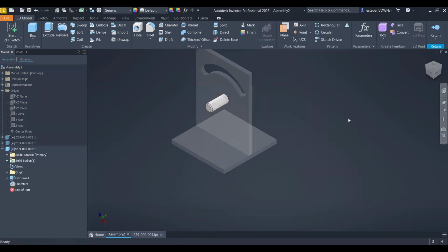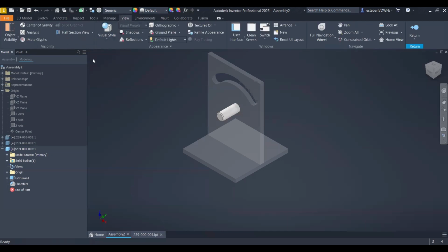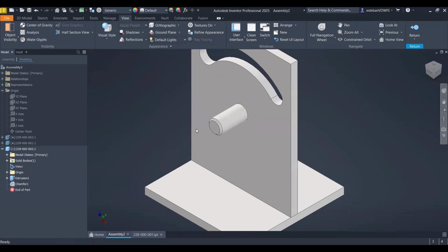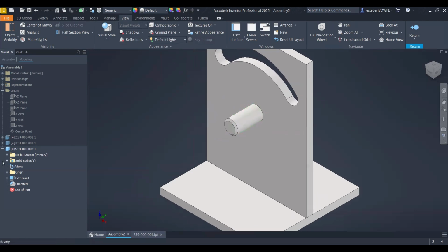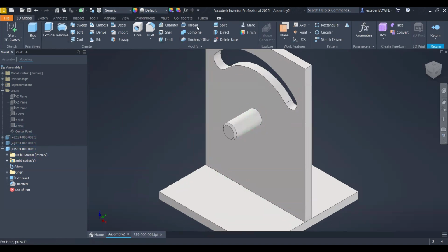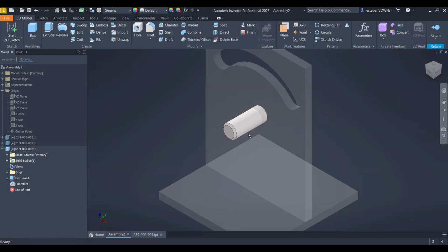Okay, so I will double click, so the rest of the thing becomes like a shade mode. Even though I think you can force the transparency as well as in SolidWorks, so I can say nope, you guys should always be solid, nothing transparent for right now. And the only way to know that we are modifying the part is because, one, I'm working on assembly and I'm having tools for 3D modeling. Doesn't sound right? And the other one is that you're going to have a grayed out of this area. As you can see, just this area is in a solid color. Okay, so let me push back this change on the transparency, and let's do something else.